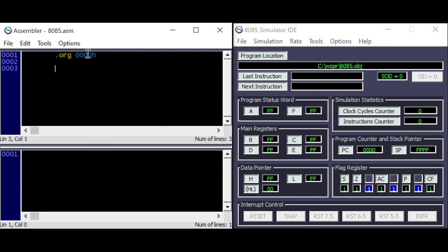That's why in your system your ROM or PROM must also begin at address 0. So, as we have seen with the reset instructions, they will call addresses between 0 and 38. It is good practice to jump past the interrupt entry points. So let's jump to label init and put the init at address 40. That's just an example.